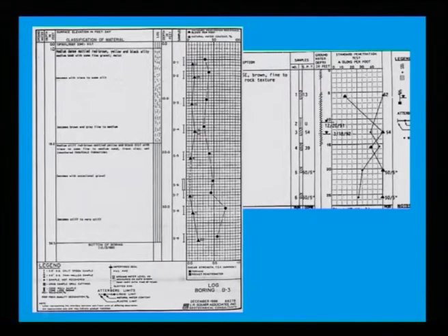Now, if you look here, it has taken a bigger one. You see standard penetration, blow count and water table has been shown, and your SPT has been shown. You can show it, you can take it out and show outside also. You can put it in annexure 1, annexure 2, so that you can visualize.